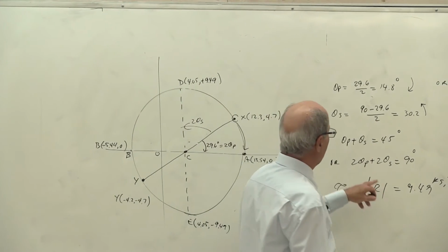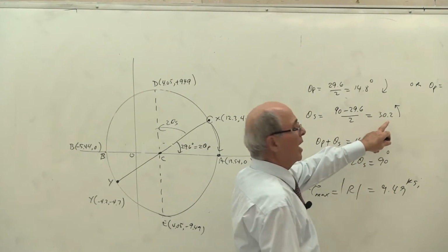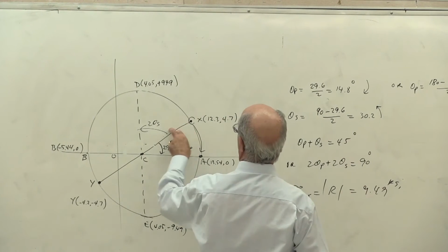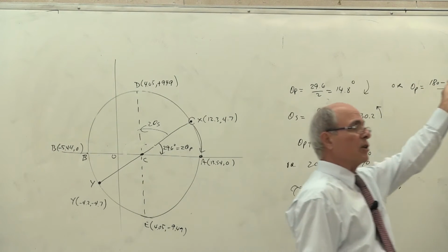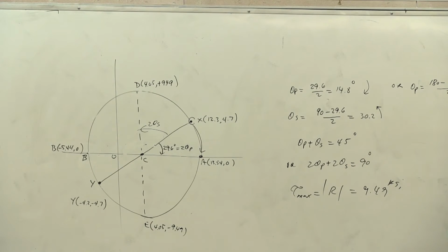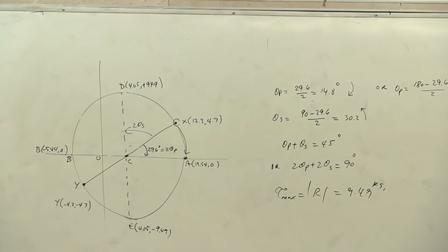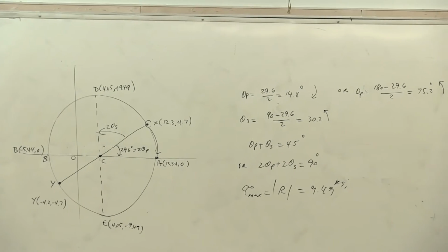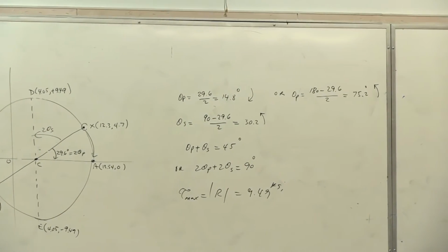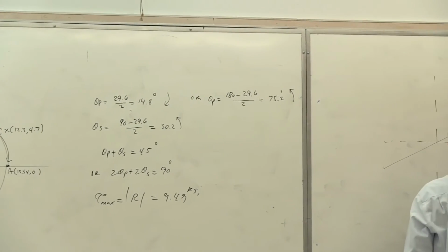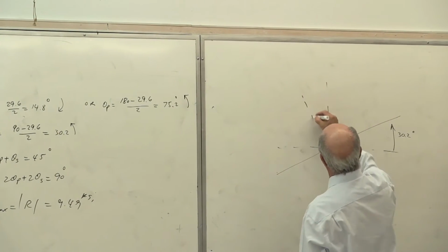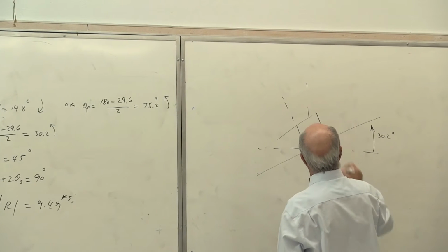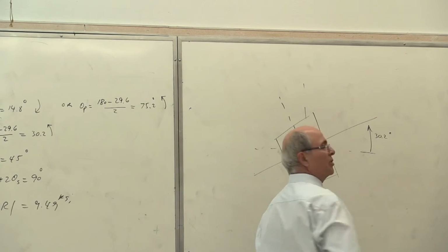So anyhow, how many degrees do I have to go? Here it becomes 60 something, here it becomes 32, but it will be counterclockwise. Yes or no? Therefore, again, you get your x and y very lightly there. This time you go a little bit more, so you are going 32 degrees. You put your two lines here and draw your element there. Is that correct or not?